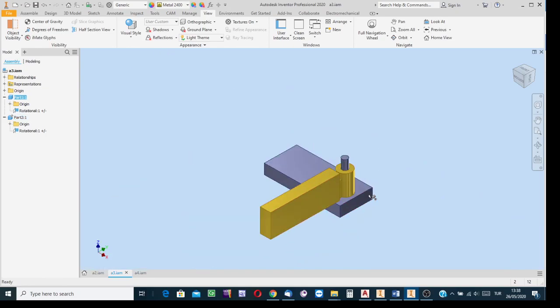In the virtual, solid model environment, to be able to explain that this component is not stationary, it is to move about the axis of the other, well, input the constraint. Similarly, at the browser, first find the icons corresponding to the components, part 1, part 2, component 1, component 2. Click on the listing arrow, and then you see the same constraint icon is in the list of both, rotation 1, rotation 1.